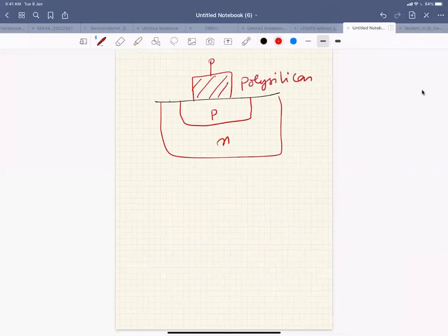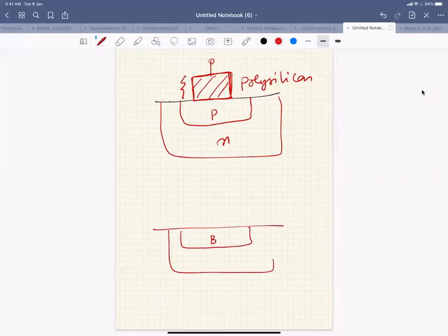Because you could dope this emitter. This is done by deposition, right? So you could deposit silicon on top of your silicon, and when you do it by deposition, you have control, right? You first define your base region, then your collector base region, then you could deposit whatever thickness you want and dope it, because we have the epitaxy process,